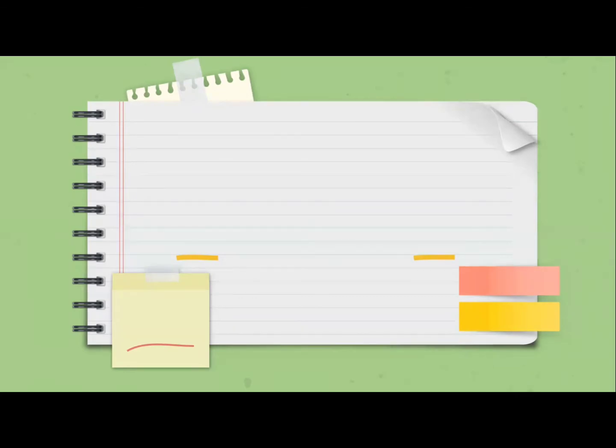For example, if a ship floats at a particular draft, any trimming moment acting on the ship will act about a particular point on the water plane. This point is the centroid of the area of the water plane, and it is called the center of flotation. The distance of the center of flotation is read with respect to either of the perpendiculars or the midship and is abbreviated as LCF.